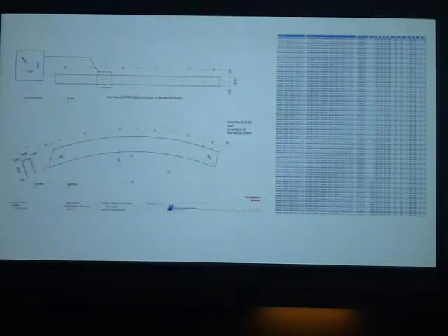When all modeling work is verified, the next step is to produce the fabrication documentation for all the parts. I will show the stiffener first. In order to efficiently communicate the fabrication data for each stiffener to the fabricator, we created a diagram with variable dimensions for each possible combination of variables. An accompanying Excel file provides the exact values for the variable dimensions for each individual part. And next I will show you how the fabrication documentation for the aluminum sheets is created.